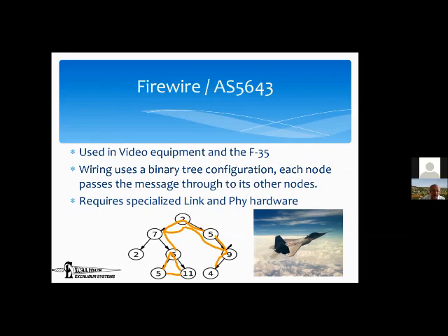There are two basic methods. One is that each one of these nodes itself will only send one message at a time. So if, let's say, 6 sends something to 7, and 7 has its own message to send to 2, 7 can decide which one to send. But in fact, what FireWire uses is a more complex mechanism having to do with timers. It sends out a timing message to the entire bus periodically, and everybody has their own time slot in which they're allowed to transmit. That's the method they use to make sure you don't have multiple transmitters simultaneously.